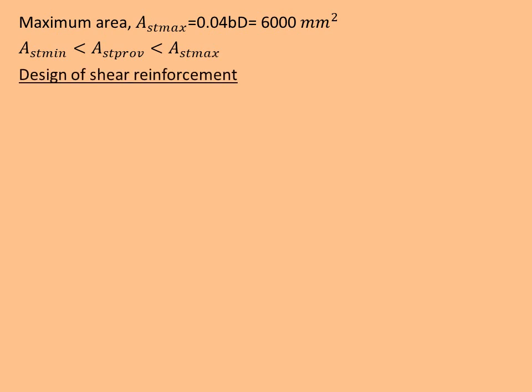Now next we design shear reinforcement, because when we place tensile reinforcements, we put shear reinforcements to hold the tensile reinforcements in place and also to prevent cracks. First we find the shear force, the actual shear force value. Here we will be using the actual load, that is 15.75, which is the total load. Total load is the actual load. The ultimate load is the point load that we multiply with FOS. So we find the actual shear force and we get 49.061 kilonewton.